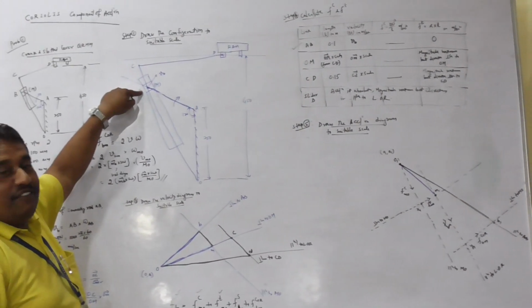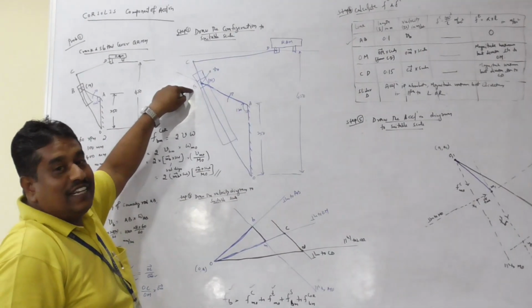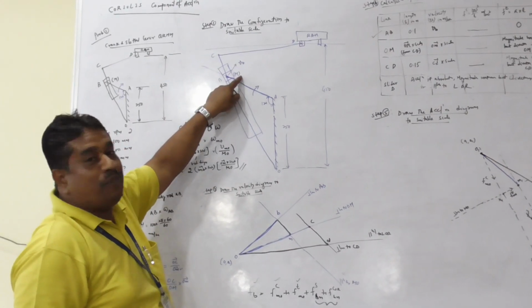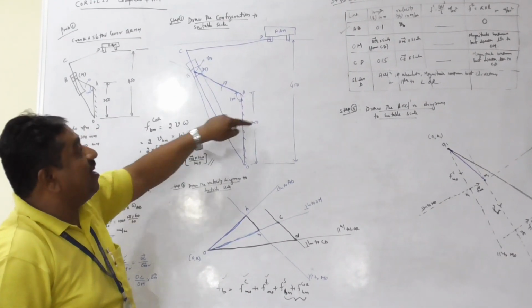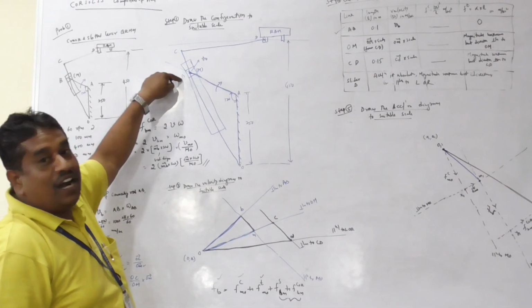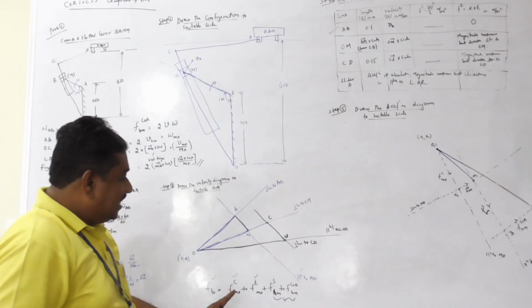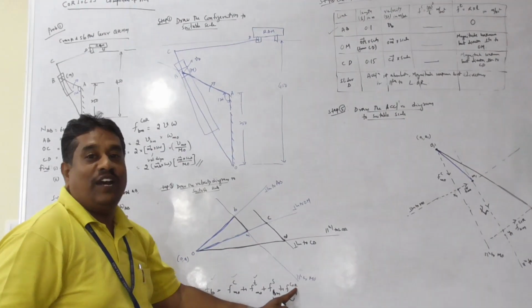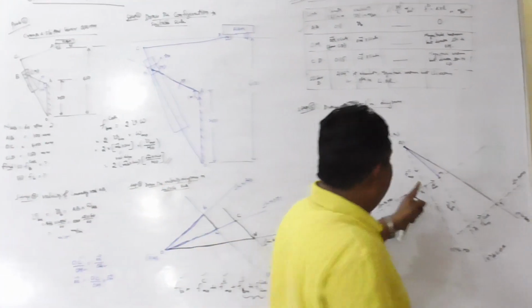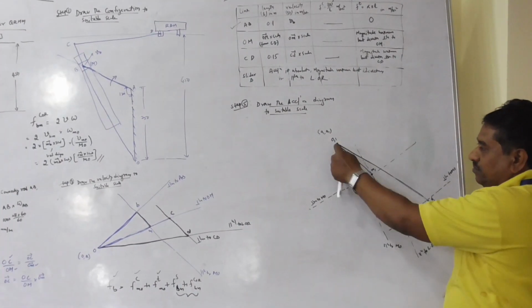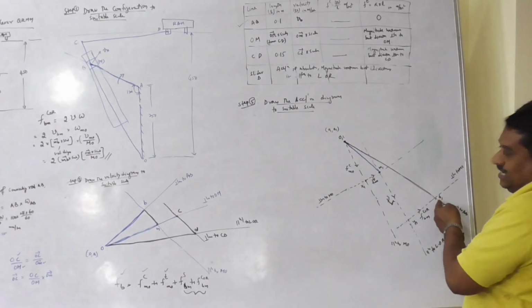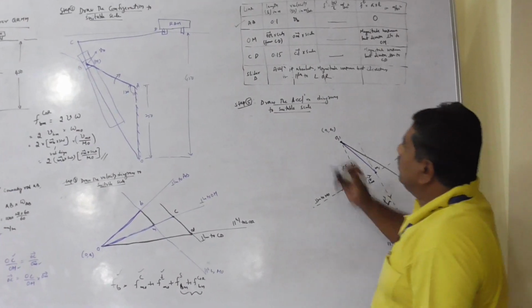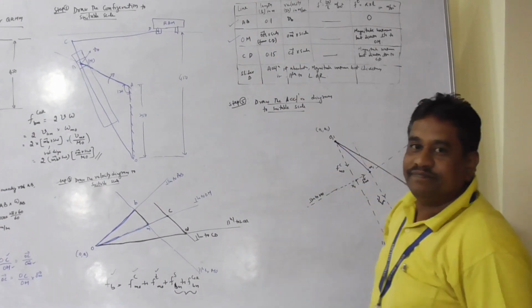Now, B is a moving point on a slotted lever. At the given instant of time, this moving point coincides with the fixed point M. Since moving point which slides on an oscillating link, moving point will have 4 accelerations: centripetal, tangential, sliding and Coriolis. That is also expressed in the acceleration diagram. Centripetal, tangential, sliding, Coriolis, the resultant like this. Now, this length is also over.